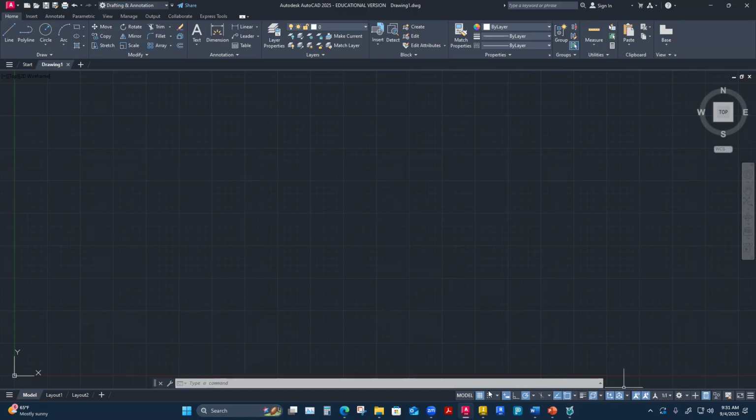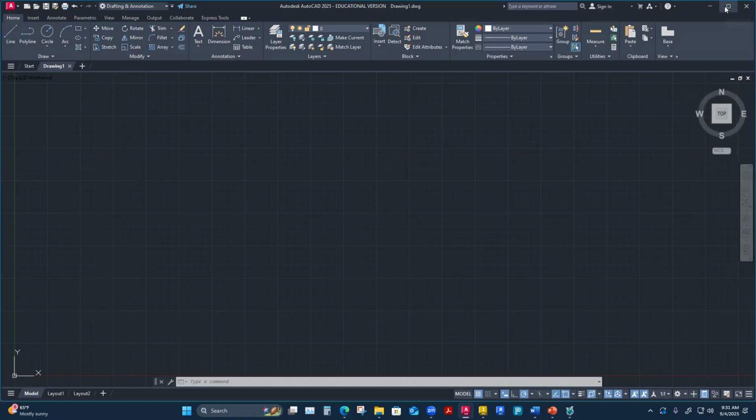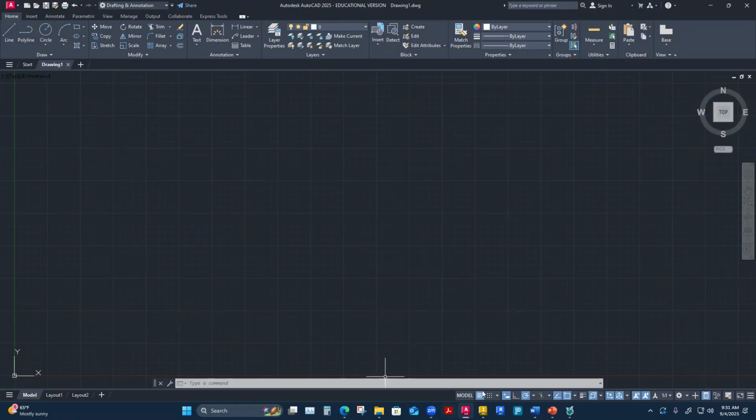What I wanted to really point out is the big toolbar at the bottom, the status bar they call it. So the very bottom in mine, I think I'm maximized. Yeah, I think I'm maximized. It's the status bar with tons of little different icons, and they're really symbols that we learn, maybe what they look like. After we learn what they do, we kind of learn that that symbol does that. A lot of these status bar icons are associated with the function keys on your keyboard.